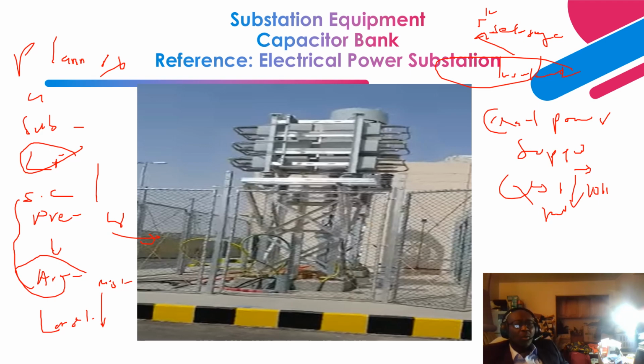It does not meet the criteria. For higher voltage, it's plus or minus 5%, utilizing the pre-fault voltage of 1.05 per unit, and at low voltages, plus or minus 10%. That is what is required.